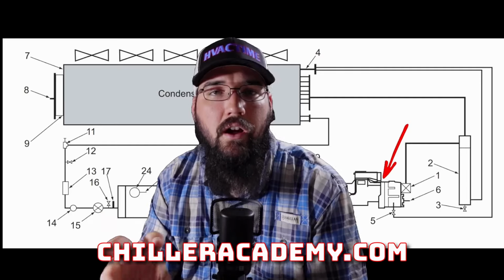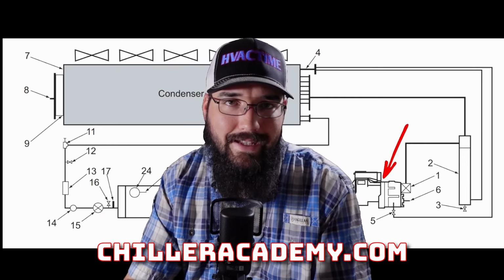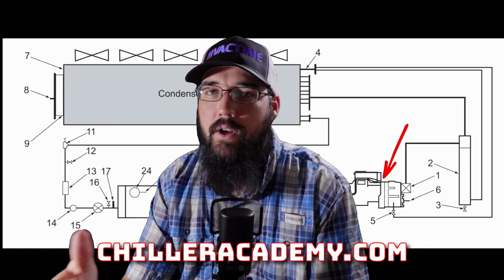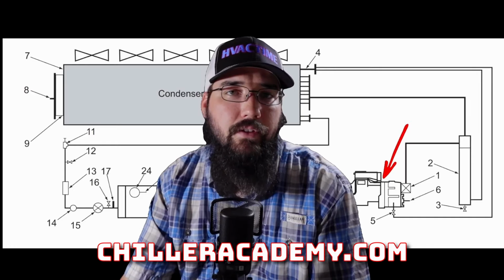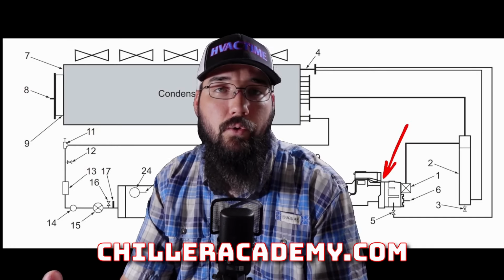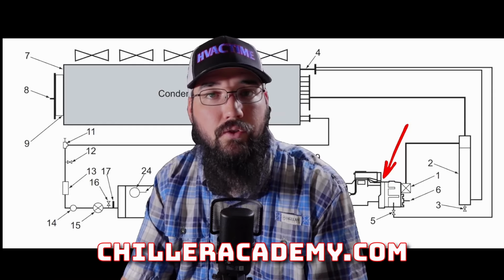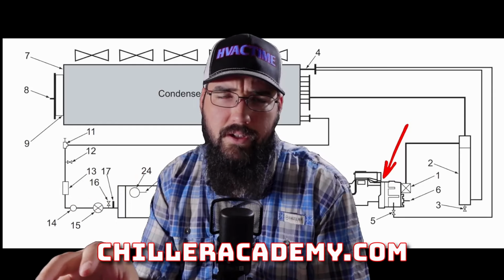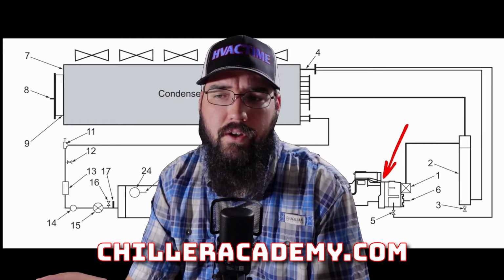But the concept of a 60 hertz motor with a minimum needed of 20 hertz would be a similar concept to whatever the hertz of our compressor is. We just have to have a minimum starting hertz in order to maintain the minimum compression we can and rotation, so that our oil flow is maintained and our motor cooling is maintained. Because all these are suction cooled, or the vast majority of these are going to be suction cooled.